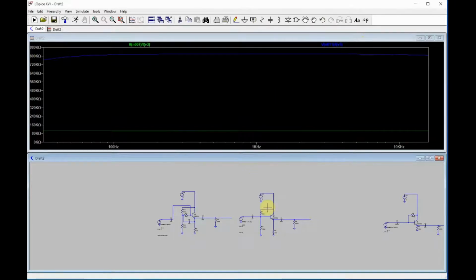Here's the first circuit right over here, and this blue circuit is right here. We've got an input impedance of 817K, almost a meg, by just adding these two parts. You didn't need to use a JFET or an Opamp, and really it's just one transistor. So this is an old style way, a little older design.